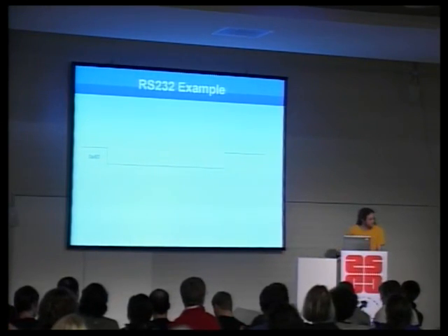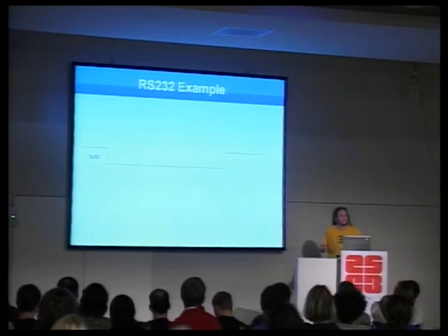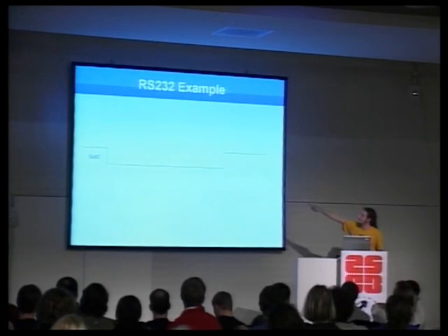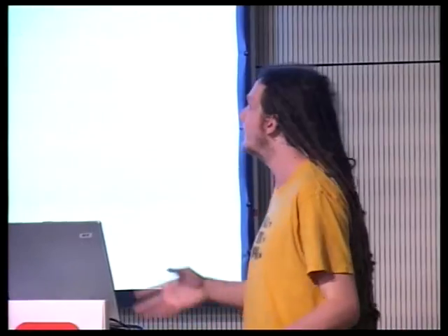For what? Make it wake up? Not quite. This is how it determines how quickly the transmission will be. The message looked, think of it as a difference between the 2 edges. If you divide that by 8, you get the width of 1 bit. So that's what it does. It times its own time by measuring the difference between these 2 edges. And that's how it knows how quickly to speak to you.